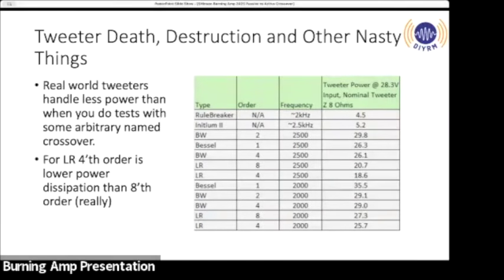I built myself a box that measured real power into a driver, and I played pink noise at the time. M noise wasn't common. I would use M noise if I did this again. And I played M noise or pink noise into it at a real power level, real actual thermal dissipation of 5 watts in that tweeter. And I basically evaporated all the ferrofluid out of it. Okay? And the tweeter impedance was never the same.